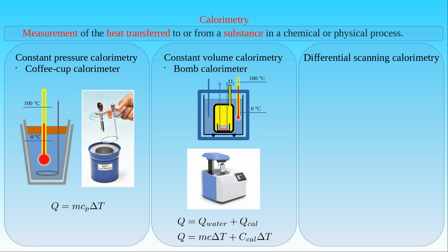In a traditional calorimeter, a sample is placed in an isolated chamber surrounded by some medium. If a chemical reaction is triggered in the sample, the difference between the temperatures of the sample and the surrounding medium gives information about the heat release and the consumption of the reaction. The differential scanning technique goes further, and uses both a sample and a reference kept under the same conditions and measures the exchange of heat between them and their surroundings. A sample and a reference material are usually in empty pans or holders which are identical.